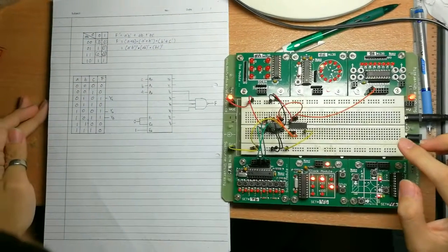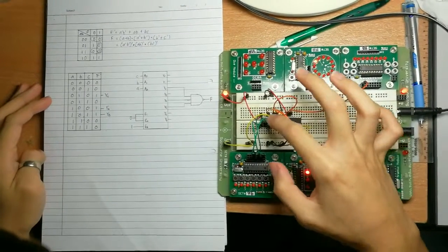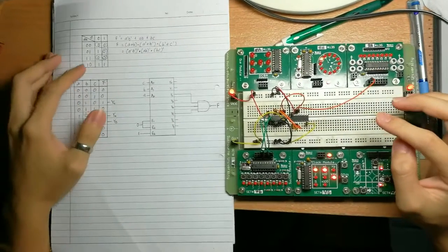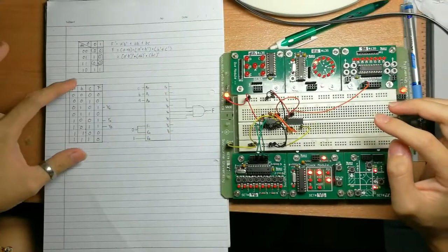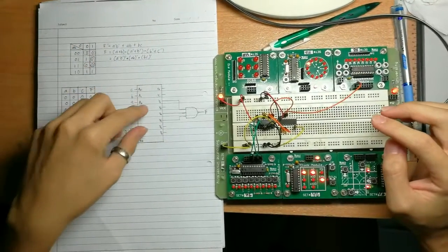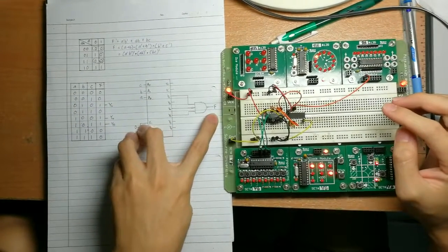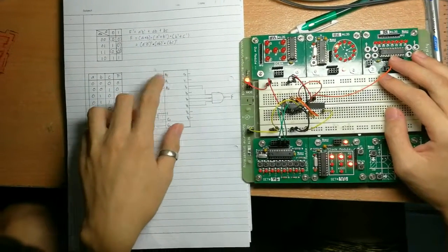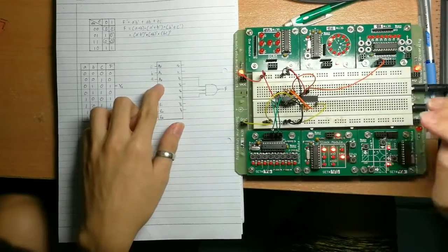This is our part 2C circuit. So this is the 74HC138 IC and 74HC10 IC. According to the K-map, we have the equation that was formed and the truth table, and this is the circuit. The outputs Y2, Y4 and Y5 are connected to the LED using a 3-input NAND gate, and address 0, address 1 and address 2 are connected to switches A, B and C.